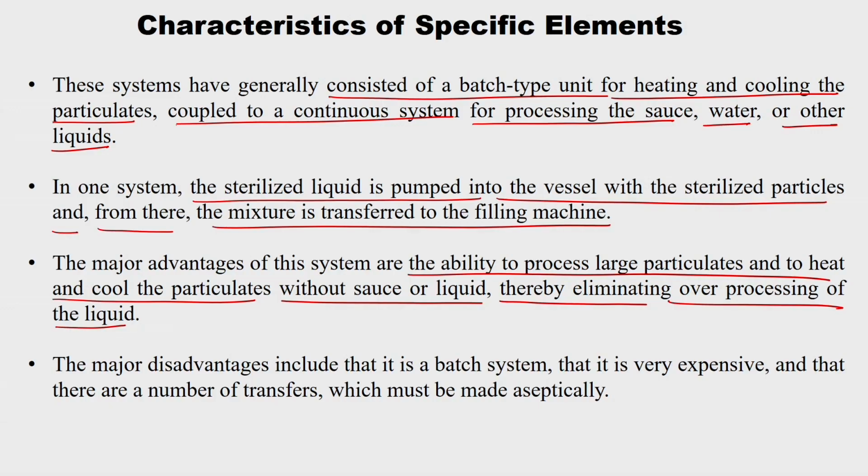For solid particles, as I have just mentioned, the heat penetration test is very important, because heating happens by conduction and the slowest heating zone also should reach that particular temperature, right. So, in that way I am doing thermal processing operations for solid particles separately and liquid separately and mixing them. In that way I will handle particulates of larger size as well as eliminate the over processing of the liquid, because the time temperature combination I choose is based on the coolest cold point in the solid, right. That may be an overcooking temperature for the liquid. So, that particular disadvantage will be avoided in this processing.